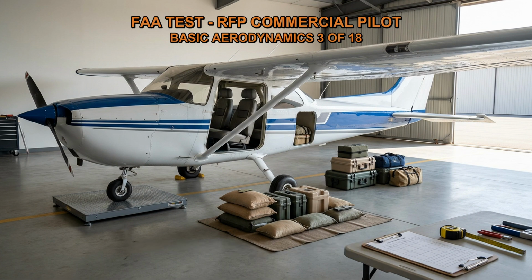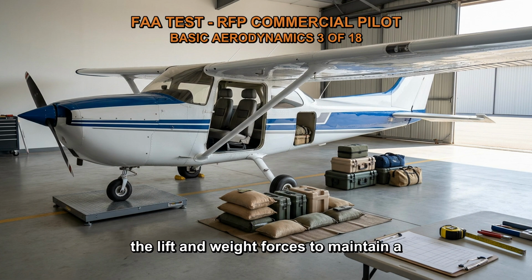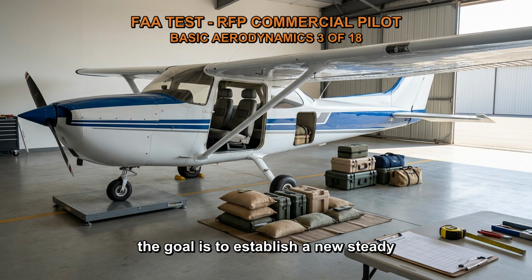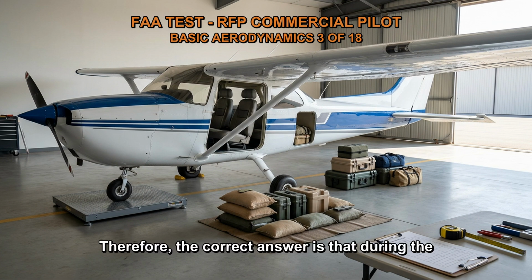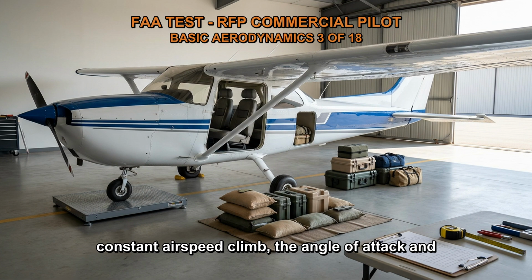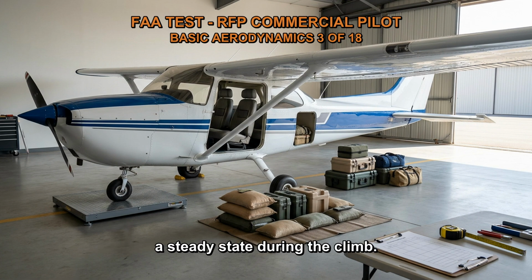typical or steady state. This is because the aircraft needs to balance the lift and weight forces to maintain a constant climb rate. While the lift-to-weight ratio may be different during the climb compared to straight and level flight, the goal is to establish a new steady state where the lift generated by the wings is equal to the weight of the aircraft to maintain the desired climb rate. Therefore, the correct answer is that during the transition from straight and level flight to a constant airspeed climb, the angle of attack and lift are momentarily increased, but lift returns to a steady state during the climb.